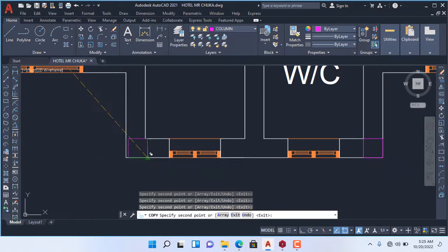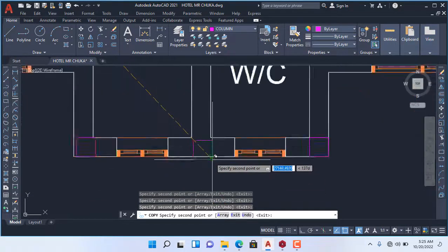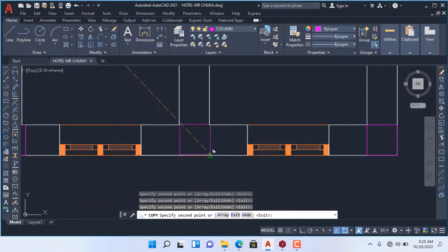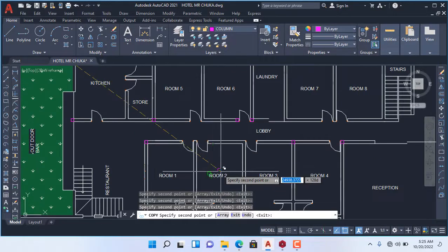As you can see, the grid is very, very important, because if you don't insert your grid, you can't insert your column in your product structure. All these ones are my column positions, so I'll need to select them one after the other.